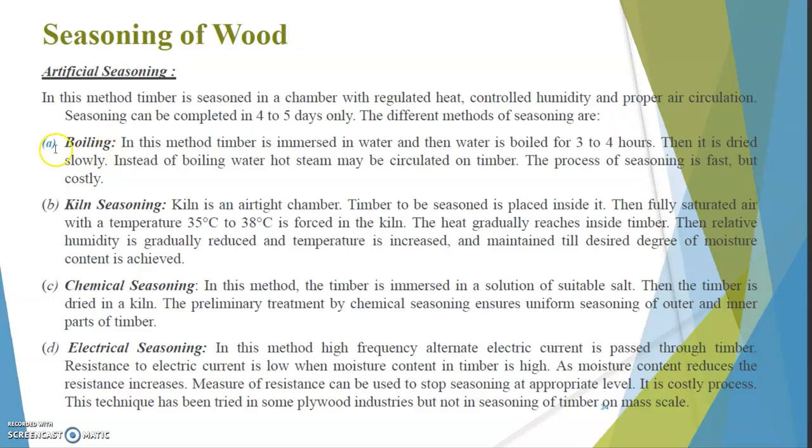The first one is boiling. Yes, heat, right? In this method, timber is immersed in water, then the water is boiled to the boiling temperature for 3 to 4 hours.